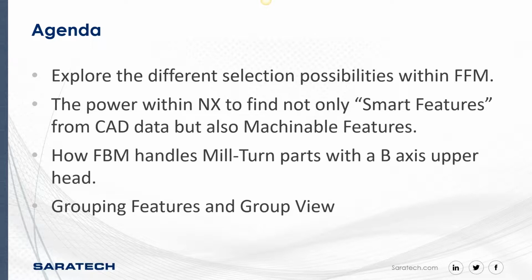But what it also does is it pulls CAD data from dumb models that have no feature tree, and it selects machinable features. Machinable features, by definition, are any 2.5 axis or below feature that has a flat surface. It will not do curvatures like 3D machining, but it will do any 2.5 axis feature, holes, anything like that, in any axis as well.